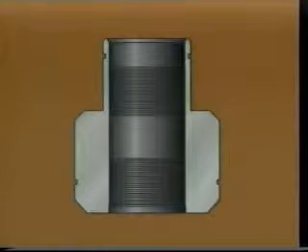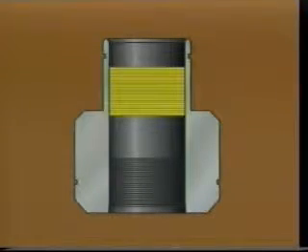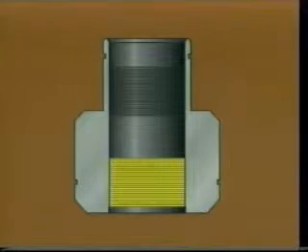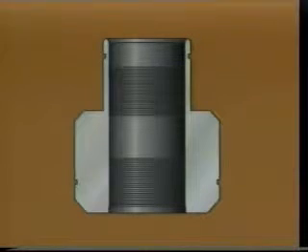Mandrel-type hangers, sometimes referred to as bowl weevils, are threaded on both the top and bottom to permit placement as the casing string is lowered into the hole. The mandrel-type hanger is a simple design for hanging and sealing off the casing. The load capacity of hangers must be reviewed before installation to determine an acceptable design. Slip-type hangers can be installed before or after the casing has been cemented, but the casing must be in tension. The installation of hangers is discussed in greater detail in your manual and also in Module P208, Casing Design and Installation.